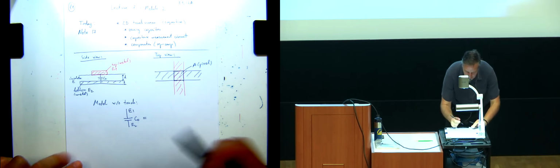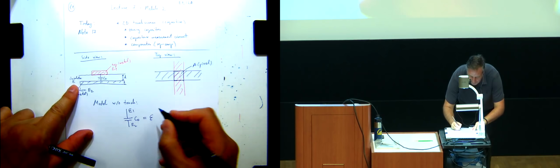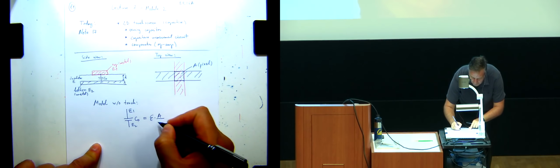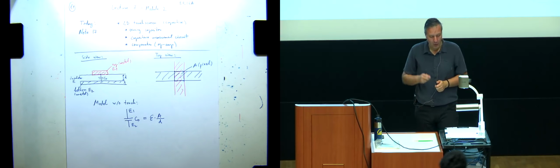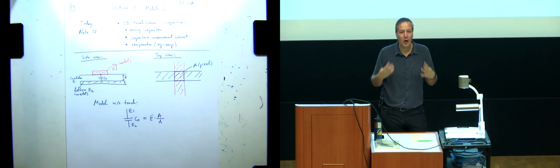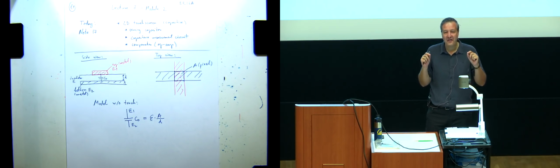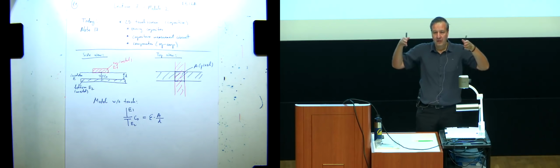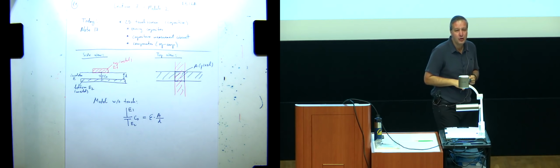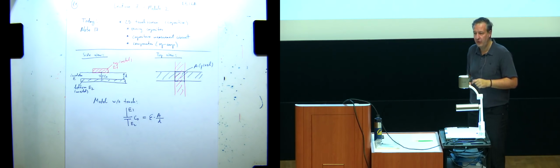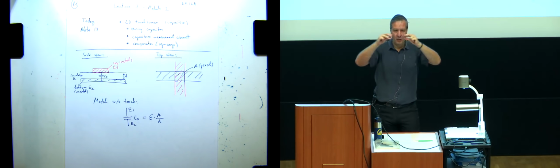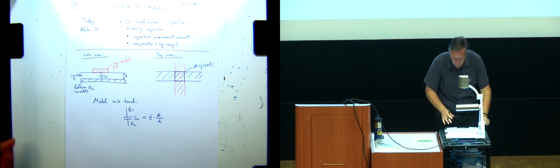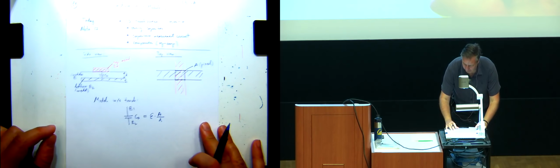Oh, okay. So the suggestion was this epsilon for the insulator times this area over distance d. Yeah, I think that's nominally what happens. There are some other capacitances from the side of the conductor down. Those are called fringe, but we're going to ignore those for now. Typically, if the conductor is thin and wide, they're negligible. But we'll see in some other cases they're not.